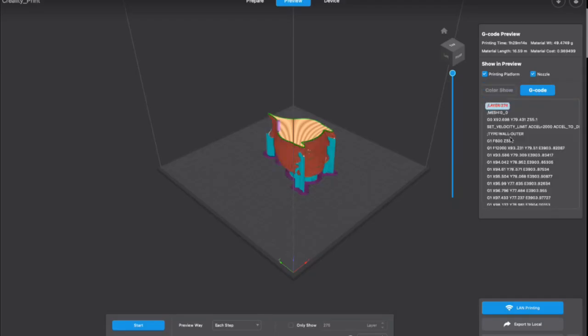So this is called G code actually. G code is nothing but geometry code. Here, this is x 93.58, y 79.309. So these two are xy coordinates. If you try to plot a graph, to plot a point in a graph we need two units, x and y, to plot a point, right? So that information was from this x and y.